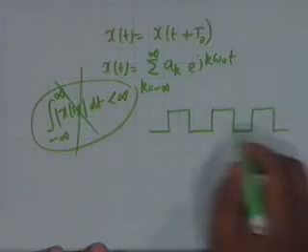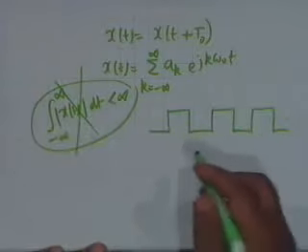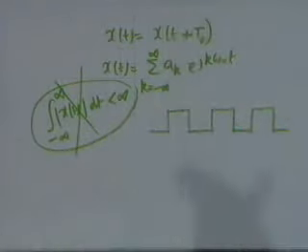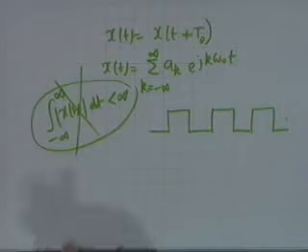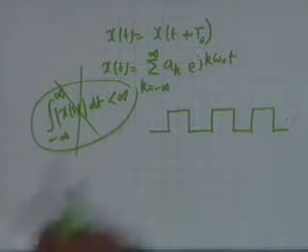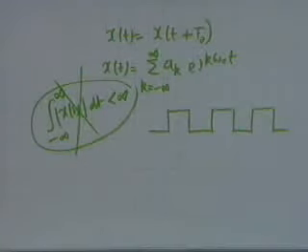It continues to infinity, and the area under the curve goes to infinity. But nevertheless, a Fourier transform exists. That's what we want to show, that it is a periodic function, but its Fourier transform exists provided you admit of a unit impulse function, that is a delta function in the frequency domain.